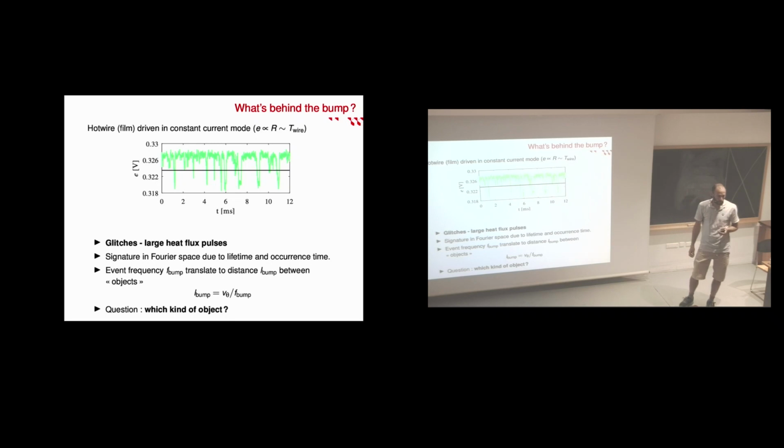Thank you. I have two questions about that. First, how is the hot wire driven? I mean, is it driven at constant temperature, constant heat flux, or what? Depends. For most of the results I've shown you before, it was constant temperature, which is the most common way of driving a hot wire. Here it was in constant current. It's easier for showing, and it was also easier to drive this one in constant current for technical reasons.